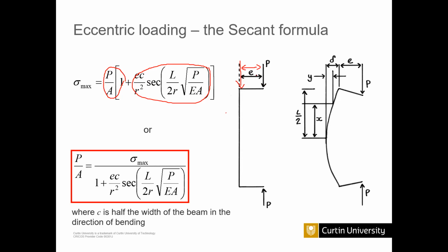This term comes up with this eccentric distance, this deflection. Sorry, this eccentric distance governs this term. If you apply the P load on the correct axis, this is the stress without any problem. So you can get the maximum stress using this equation. That's the thing you need to easily understand in here. I mean, you can get the rough idea with that.